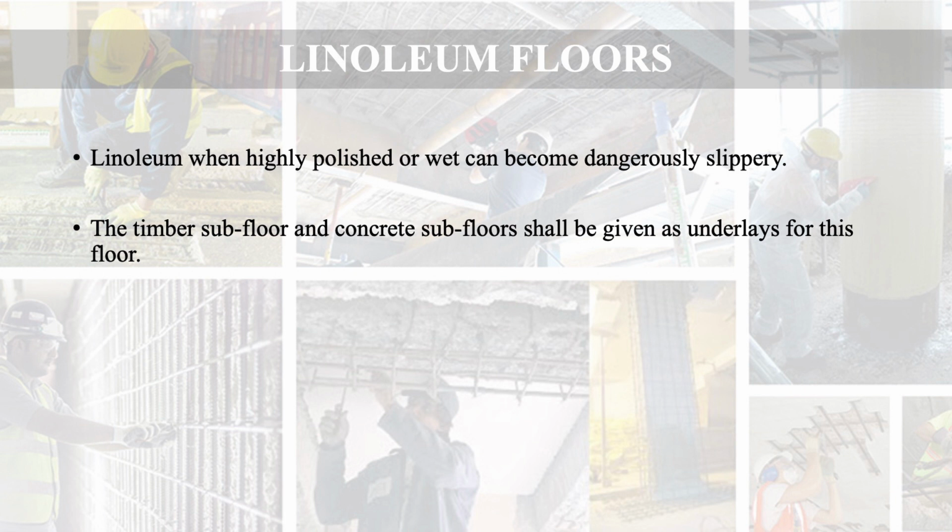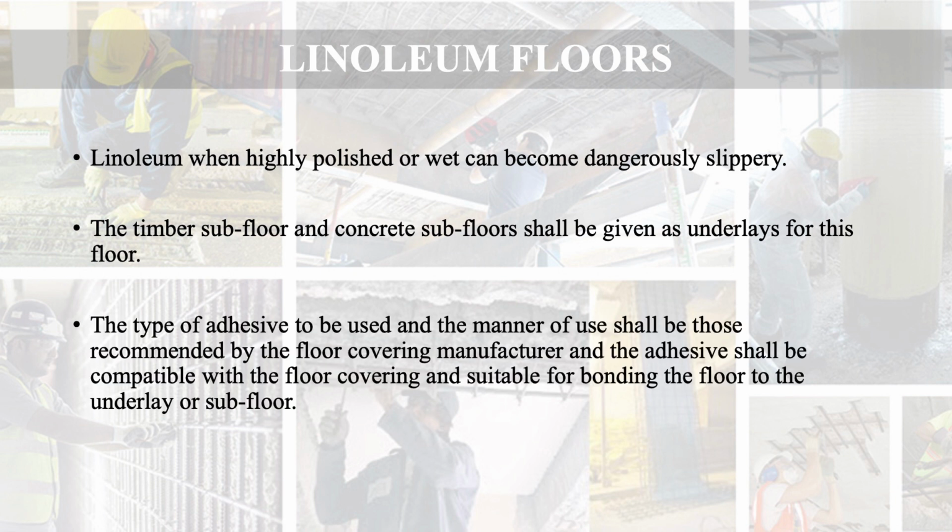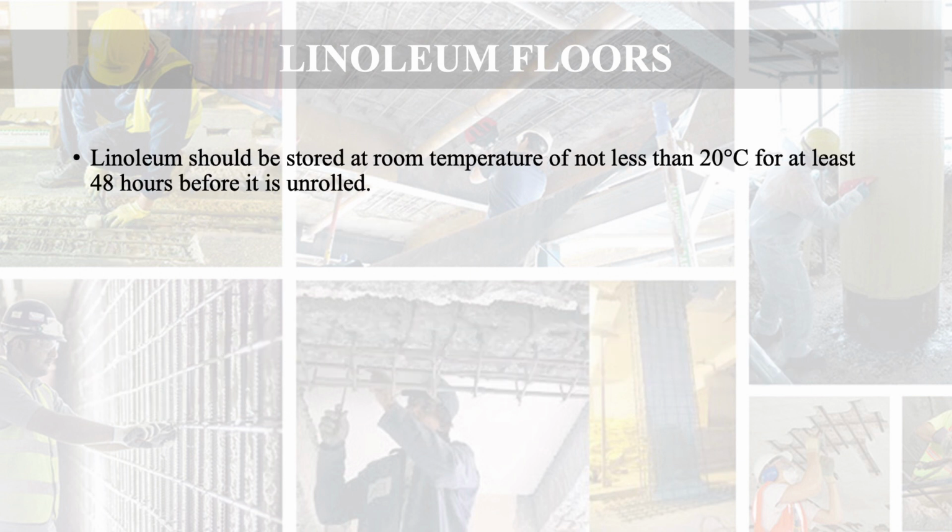The timber subfloors and concrete subfloors shall be given as underlays for this type of floor. The type of adhesive to be used and the manner of use shall be those recommended by the floor covering manufacturer, and the adhesive shall be compatible with the floor covering and suitable for bonding the floor to the underlay or subfloor. Linoleum should be stored at room temperature of not less than 20 degrees centigrade for at least 48 hours before it is unrolled.